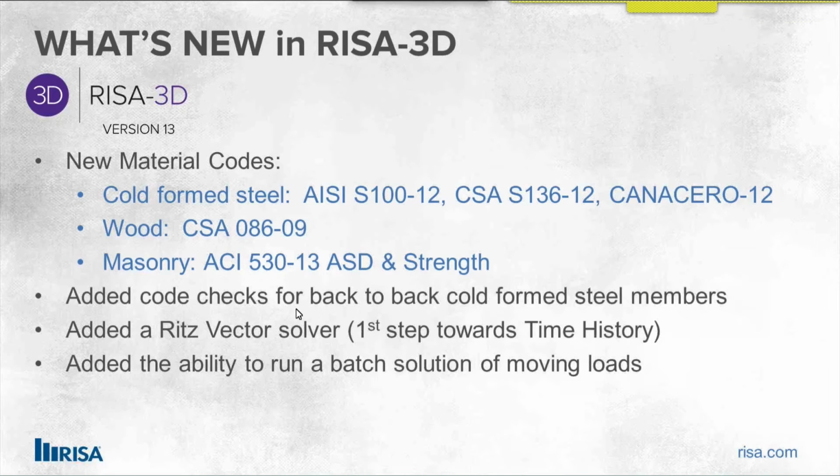We also added some additional new features to our moving loads. It used to be that you could run a moving load at a time, but now you have the ability to run a batch solution with moving loads, which is really handy when you're trying to figure out, is the moving load the governing, or are the static loads the governing? So you can actually take a look at that as well.